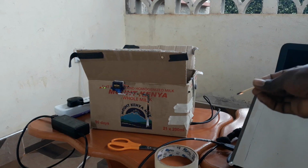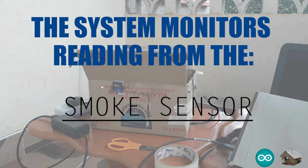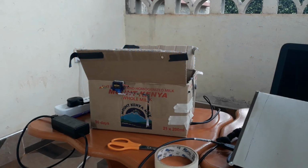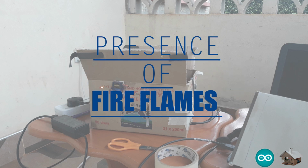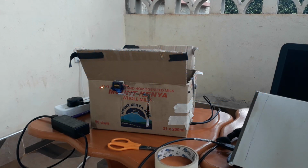Our system basically keeps watch over 3 things: monitoring the readings from the smoke, flame, and temperature sensors. In case there is a fire incident in a building, we expect that these 3 variables will be altered. For instance, the smoke concentration will rise, there may be some flame, and the temperature values in the building will rise. When the readings from the smoke, temperature, and flame sensors rise too high above the set threshold, then probably there may be a fire outbreak.